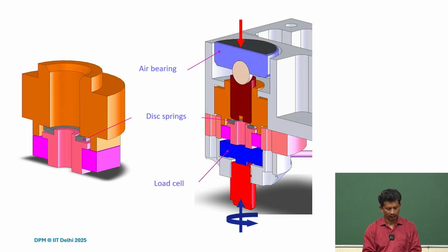So we tried to implement that, and what you see is the air pad here, the air bearing. The granite block is on the top. This black part is the porous air pad through which the air is flowing out. What we also see here, and that's very important, is how we are supporting it. So we created a spherical joint so that it can self-align.